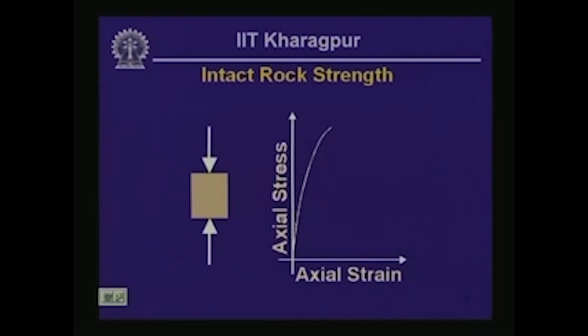and you can see that the stress strain curve is trying to bend over to your right. So, this is a nonlinear stress strain response that we are looking at in this case. The stress strain curve is going to bend further over, and it is going to become almost horizontal with no further increase in the stress possible.